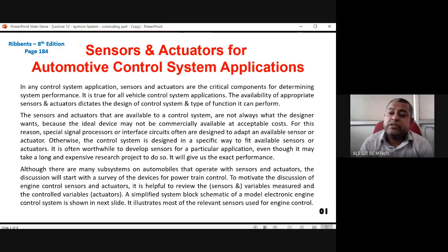Nowadays microcontrollers are there. They know the engine capacity and what all can be done with the engine, and depending on the input condition, the microcontroller takes decisions accordingly. Yesterday, when I was discussing ECU, I told that in a very primitive or simple kind of ECU, 16 different cases of engine operations and 16 different cases of load variations are already input.